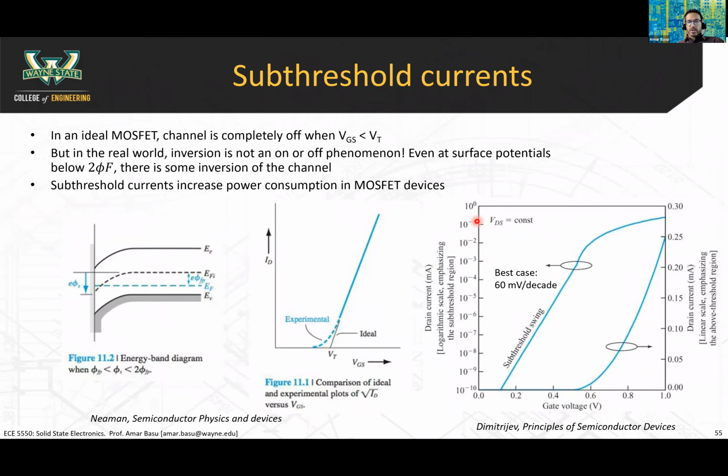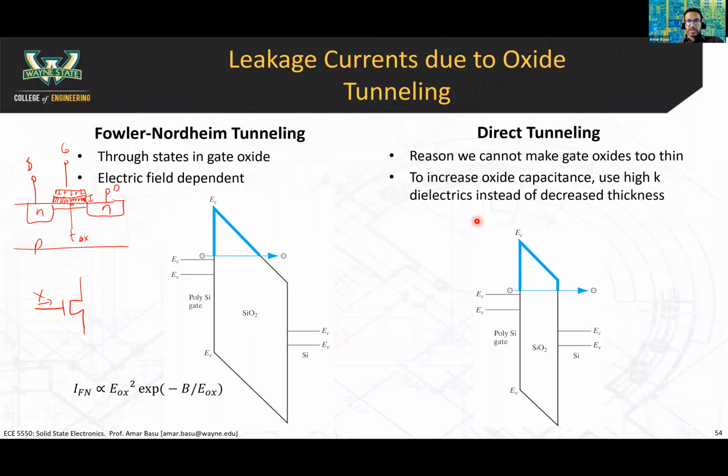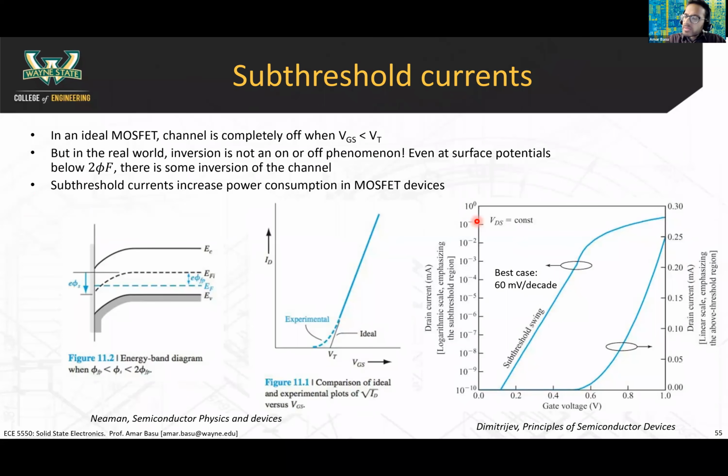All right, the last thing we'll talk about today is subthreshold currents. I'm just giving you some minimal level of exposure to this so that you know what this term is when you start talking about it in a future class, if you end up going in this area. Subthreshold currents are very important for the reason that we alluded to earlier. Basically we said that in order to maintain constant field as we shrink down the size of the transistor, we also have to shrink down the voltages. When we shrink down the voltages, though, the problem is that your voltages start to become smaller than the threshold.